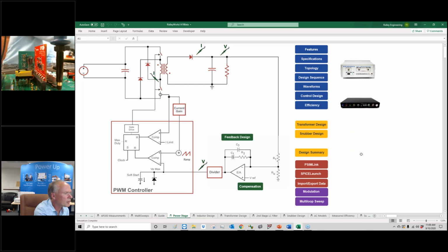Is there a fundamental way to measure the primary inductance? Yeah, we showed you how to do that. You need a frequency response analyzer. I don't know how anybody designs without a frequency response analyzer because it's kind of pointless. When I was in school, in the early 80s, you made your own frequency response analyzer. You had a signal generator, which you can get in a scope now, and you just plot the waveforms. So you measure inductance and leakage inductance by sweeping the frequency.